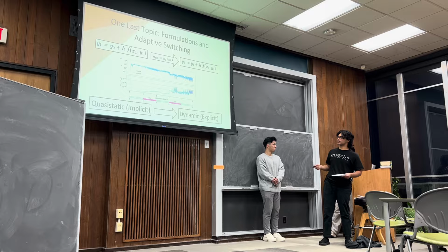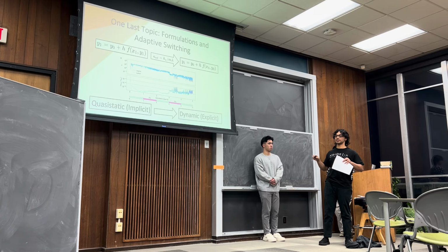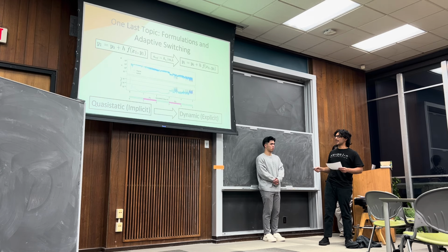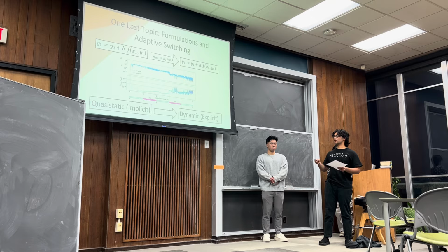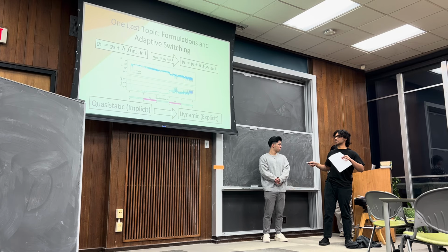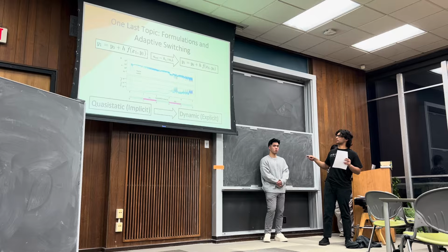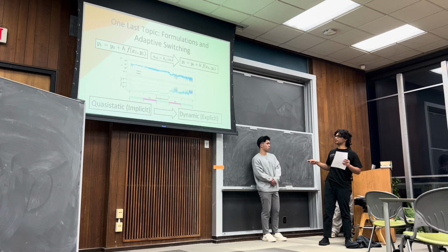Quasi-static, if you recall from physics, is like static, which means the net force on a node is zero. We say quasi because we approximate it to be zero. It's not exactly zero, but that's what quasi-static is. Most of the movement on a thin sheet is going to have acceleration or force that is generally zero, I'm just moving it. But when a node gets past a certain reference acceleration we define with the spring constant, we switch to a dynamic regime. This allows us to get a higher order of accuracy.